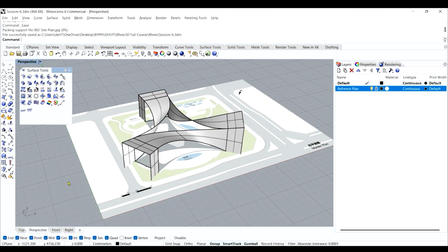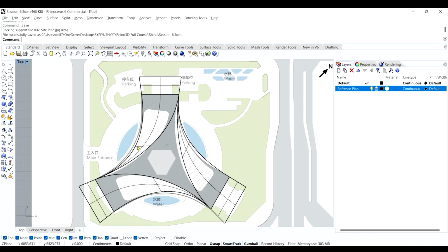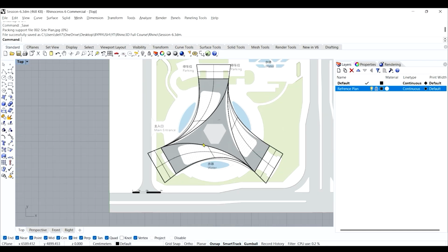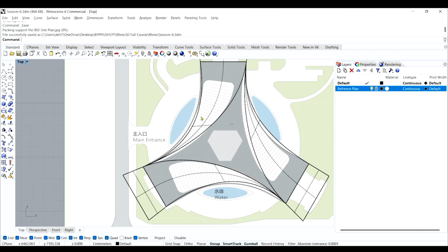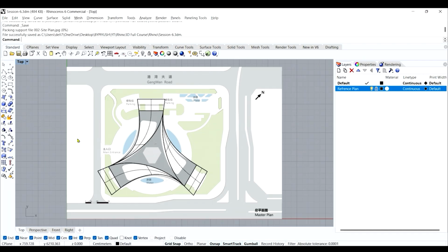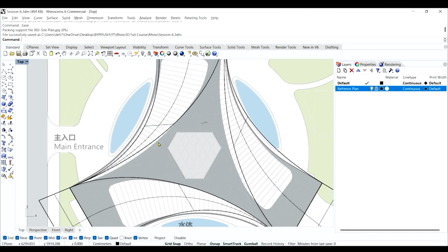Now let's go to the top view. Let's cut this off. Top view. Now if you see, the profile which we have made is almost not matching to this. A little bit of minor changes are required in this. For that, what we can do is, let's bring this in front. I will use the control points to set my curve to this side plan, and adjust my curves based on the plan which I have.